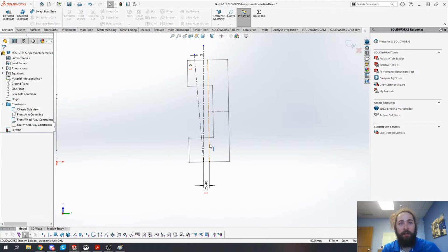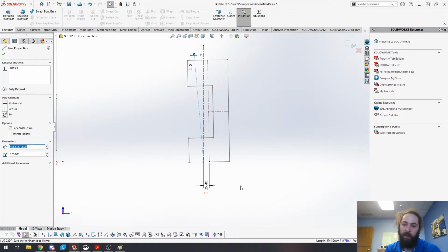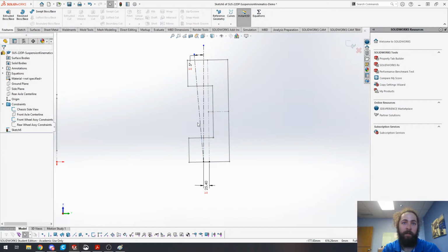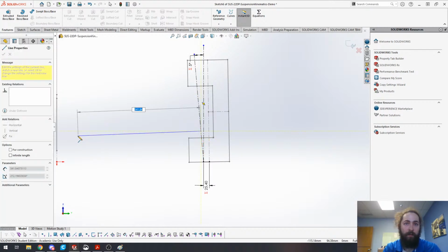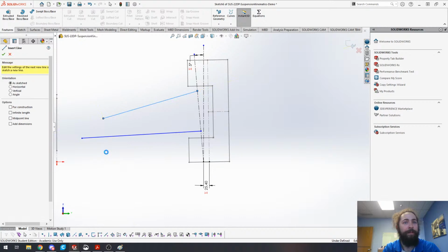And then along this line is where we're placing our outboard suspension points from the front view. That's where they're going to end up. If you look from the front, you'll see that there's going to be a suspension point. There's going to be a control arm going this way, and then there's going to be a control arm going that way.